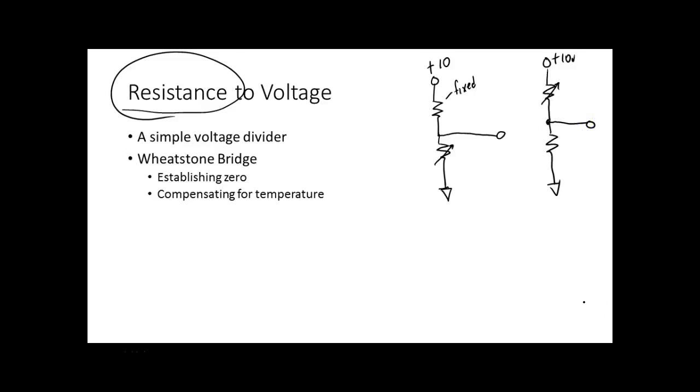So now my sensor is going to give me a what? It's going to give me a voltage that's going to be proportional to, depending on the resolution and the accuracy. Now when we figure transfer functions, guys, we're figuring it exactly, right? Hopefully you understand that just about every sensor has an accuracy measurement. It's going to be a plus and minus type thing, like plus or minus 1 degree for a temperature sensor. But we can't deal with that. All we can deal with when we calculate our transfer function is to say this is what we should get, but in actuality it might be slightly different.